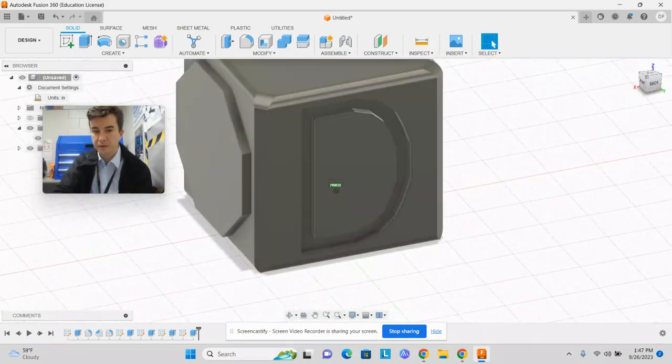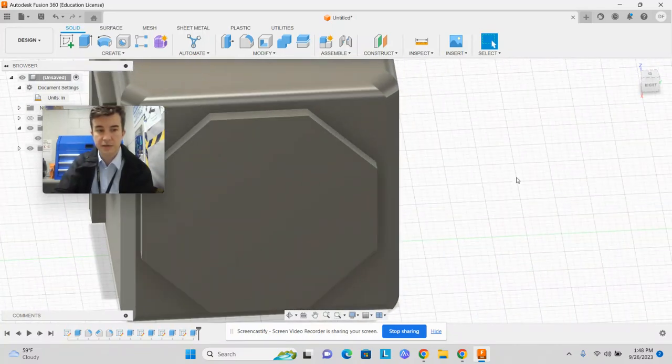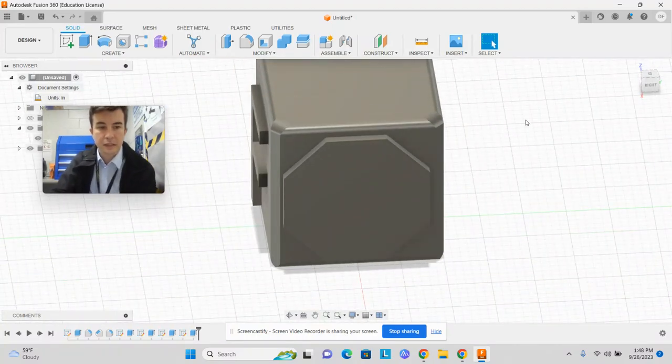And one change I want to make is perhaps this object were to be mounted on some sort of plaything like an abacus or a piece of metal. So we're going to put a hole through the whole thing. There are two ways we could do that. We could do a sketch on the top and extrude the whole thing through, but we're going to try a new tool.